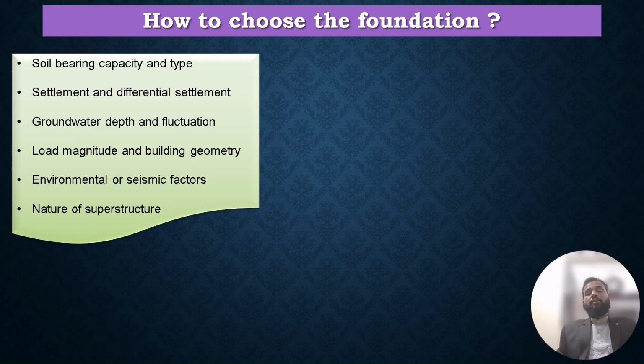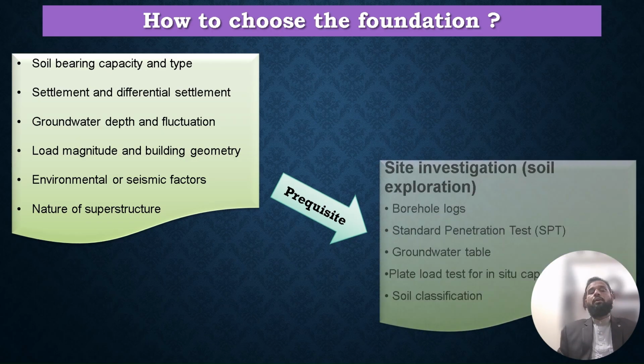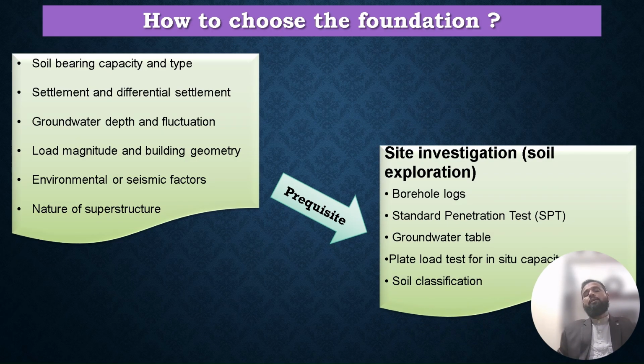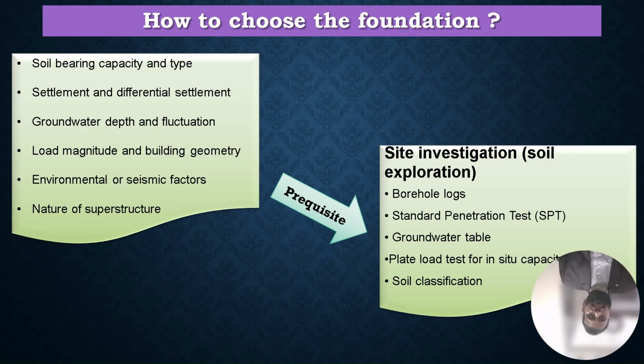This is directly related to soil exploration, or we can say that the foundation engineer must have prerequisite knowledge of the soil and how it will behave. For that we need to understand soil mechanics. These are the basic tests normally carried out on the site while we construct any foundation: borehole log, standard penetration test, groundwater table, plate load test, and then soil classification. It depends upon the foundation that we want to construct, so we will go for these types of tests.